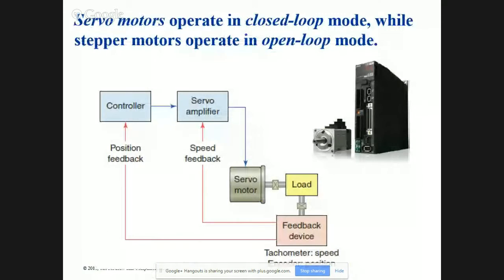Servo motors. They have amplifiers. They'll have a tach on the back and a feedback device and probably a separate controller. The PLC will just communicate with that controller and tell it a position, and then the servo controller magically moves it there and tells it, yes, I am in position, do your thing.